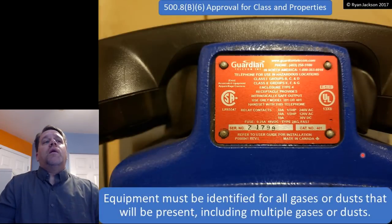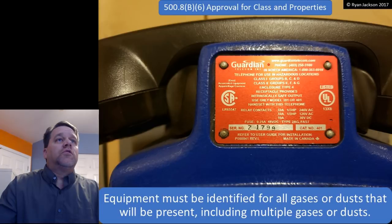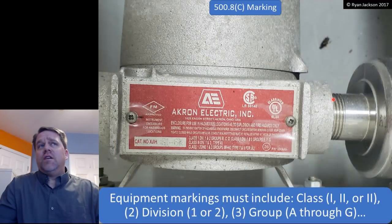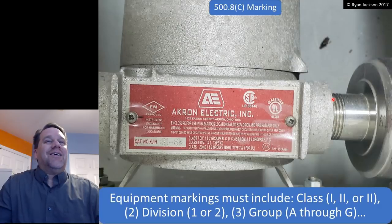B6. Equipment must be identified for all gases or dust that will be present, including multiple gases or dust. So here we have an explosion-proof telephone. Class 1, Groups B, C, and D. Can't use it in Group A, right? Class 2, Groups E, F, and G. Perfect. The next thing, 500.C, marking.